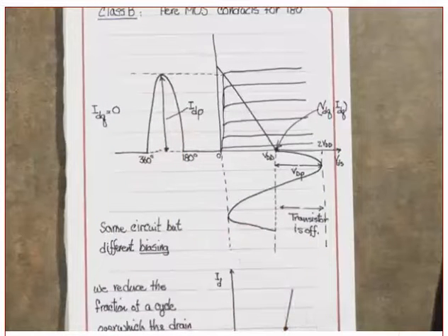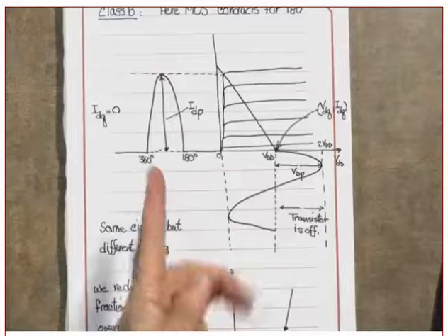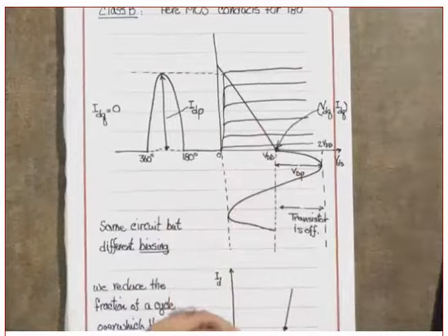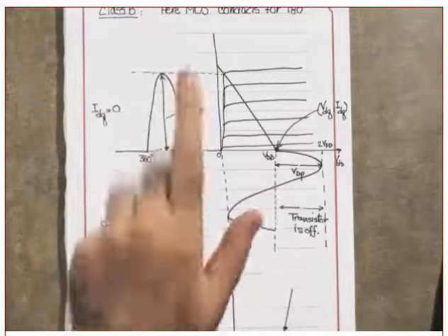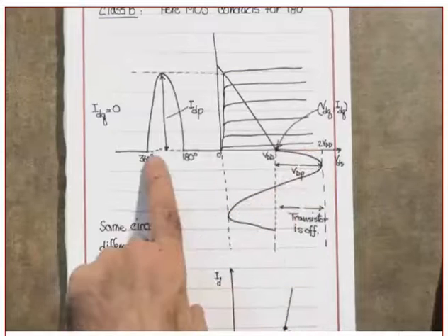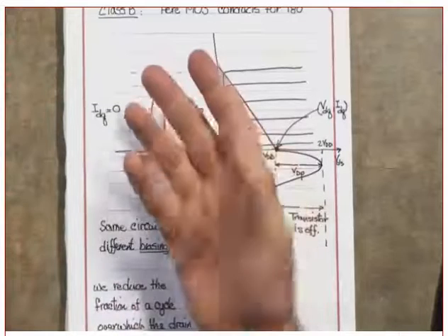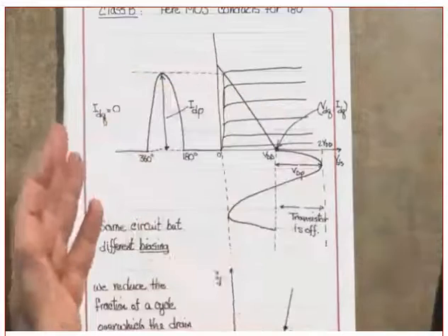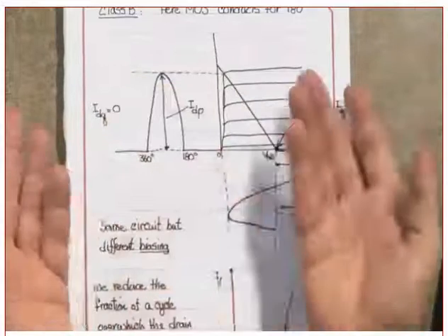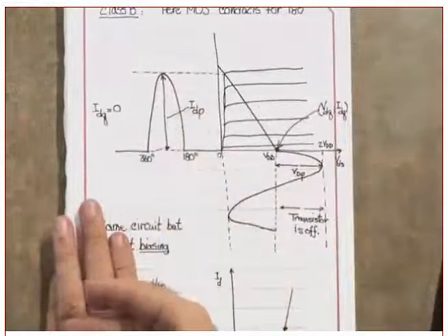What am I getting? By the way, is it periodic? There is hesitation which is troubling me. Is this periodic? This is periodic. This one also is periodic. But is it a sinusoid? It's not a sinusoid. Think about it as half-wave rectified. Did you get this or not? Half-wave rectified. But can I represent it by a Fourier series?